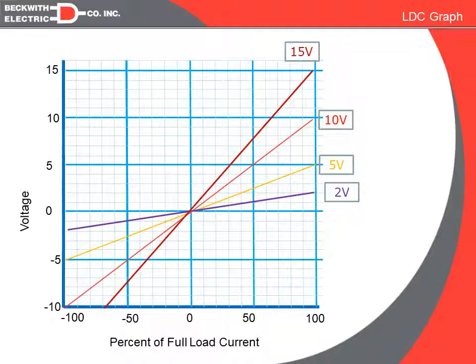If it's due to regulate in reverse or regulate in reverse measured, then we would not need to flip the signs, because we are saying that the source is now changed in reverse power mode and that the current is still flowing in the direction from the new source to the load.